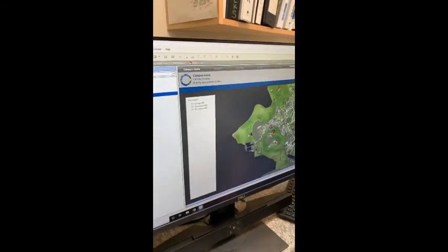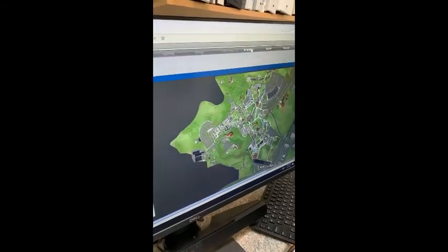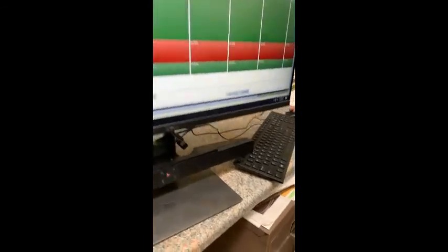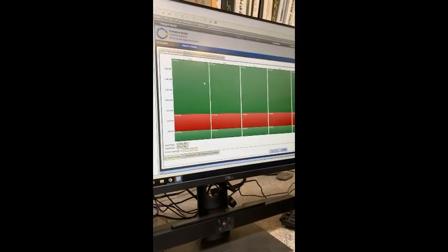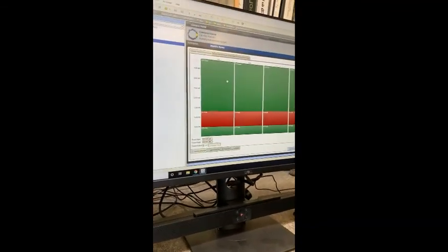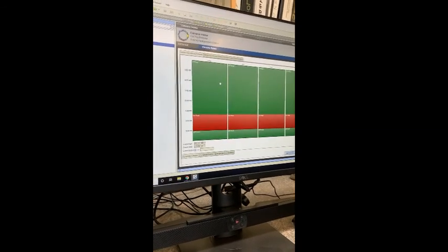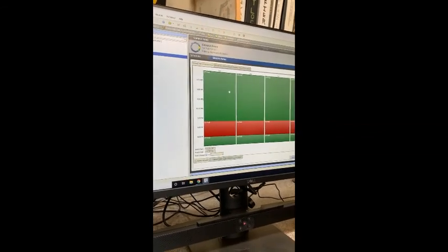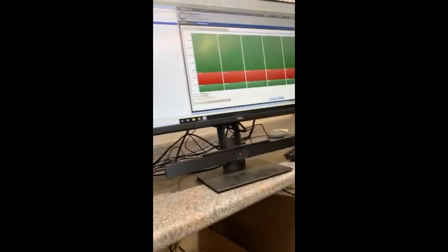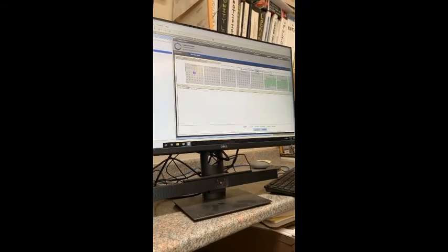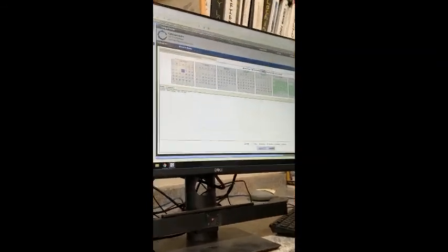The campus home, when you're looking here and you see the schedule, this is actually a different schedule. This is for setting the peak usage time for that energy system, because it is the same across the campus of this system, and that load shedding. So this schedule tab here, when you're on the campus home, is when you set your time of use, and then you can have a summer time of use, winter time of use, and determine what those days are of summer versus winter.